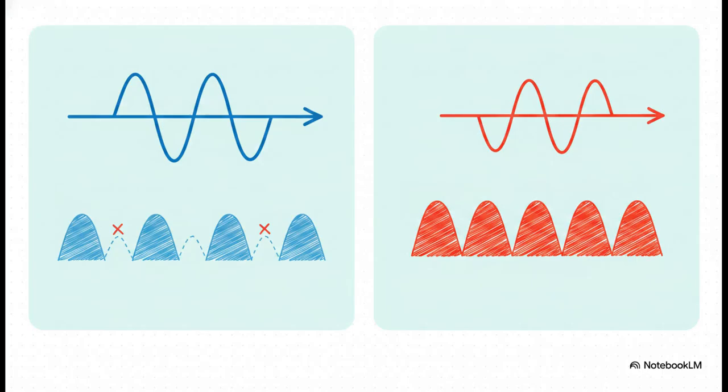When you compare the two approaches, the efficiency upgrade of the full-wave rectifier is just undeniable. A full-wave rectifier is specifically designed to allow current through the load during the entire input cycle, not just half of it. Because we're actually capturing both the positive and the negative alternations, our output frequency effectively doubles. To put that into perspective, the average value you'd read on a DC voltmeter is literally twice as high for a full-wave rectified voltage compared to the half-wave version. It's just a massive, massive upgrade.